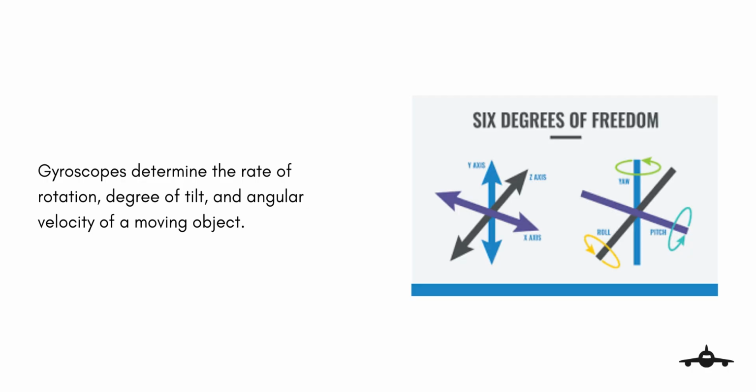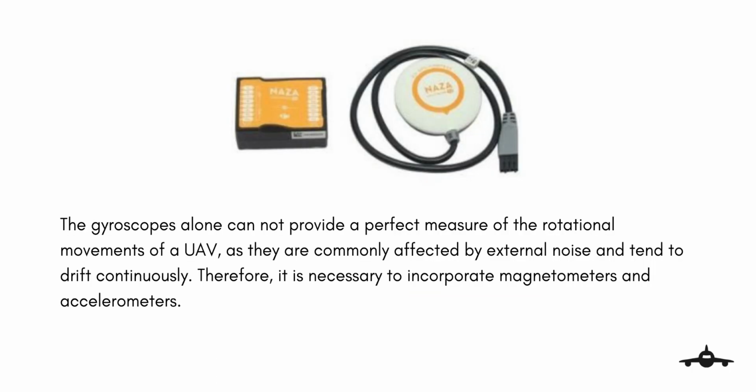MEMS-type gyroscopes are commonly affected by various sources of error. The most common one appears when the gyro presents a measurement different from zero even though it is immobile. This error influences the calculation of the angles of inclination through methods of numerical integration. This factor can be corrected by determining the offset present in the measurement over an extended period of time in a still state.